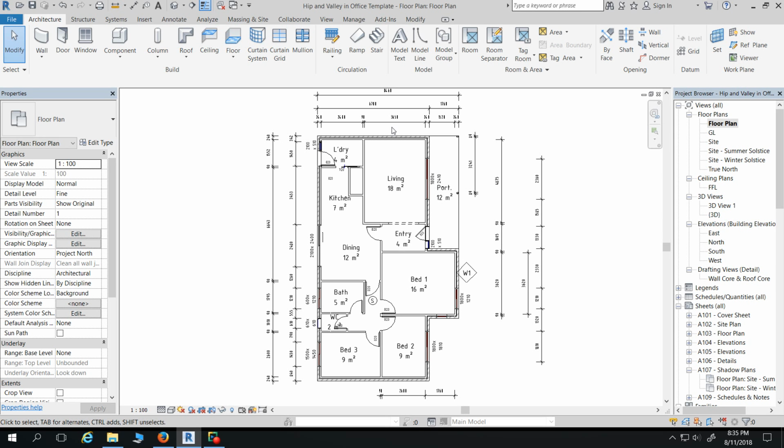Just got to go that way. So you want to add a flat roof there. I'll show you the one. So what are you doing there? Yeah, I just do it by footprint because it's just a case of using the rectangle tool and going click, undefine the slopes, 5 degrees done. I did it by extrusion, but. So what's on that one? Yeah, minus 500 or something maybe.